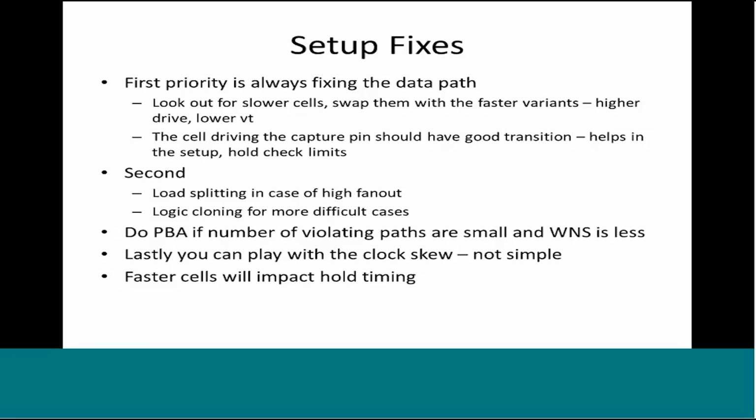It will help in two aspects. It will help reduce the delay for that particular element, plus it will make the transition faster, which in turn makes the setup constraint smaller. The constraint will also become smaller because the setup and hold constraints both depend on the clock transition plus the transition of the data pin.